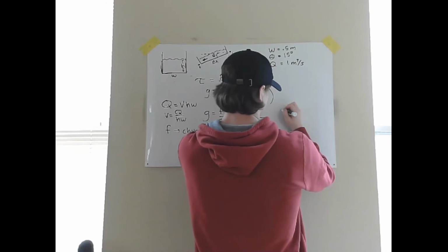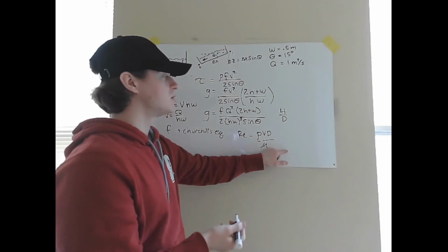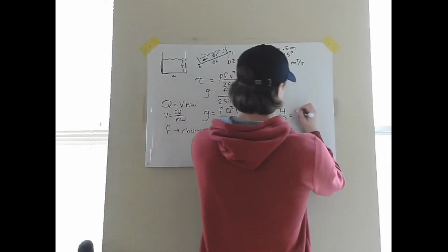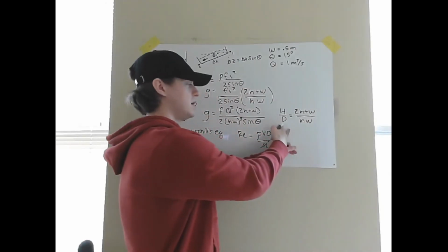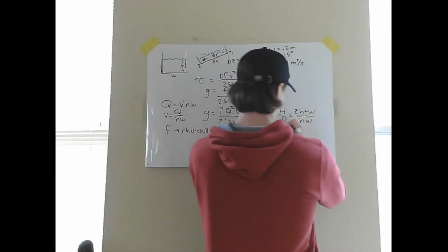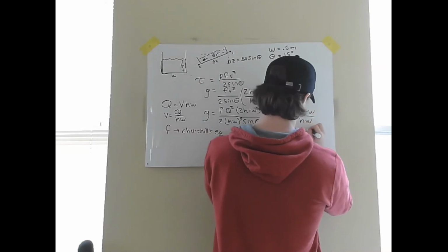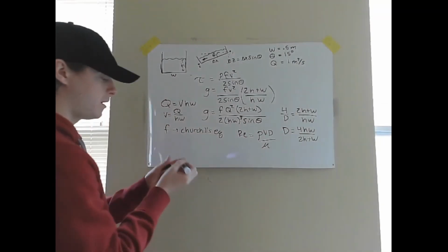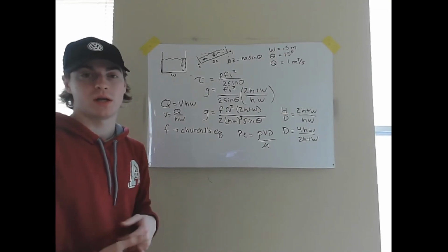If you remember, the ratio of the wetted perimeter to the area for the cylindrical pipe was 4 over d. If we set that equal to the wetted perimeter divided by the area of our channel, we can solve for d and then use this value to compute the Reynolds number. Just doing some more algebra, we get 4 times hw over 2h plus w, and this becomes the diameter that we're going to use. So now we have all the pieces we need. We just need to move to Python and code it.